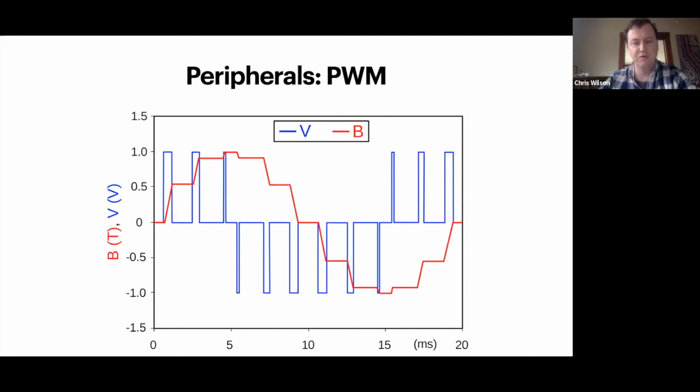If you filter that a little bit through a capacitor and resistor, it will approximate an analog signal. So if you want to dim an LED, or drive a motor where you want to increase the brightness of the LED or speed up or slow down the motor, you'll sometimes just drive those with a PWM instead of the expensive circuitry you would need to give it a true analog signal.